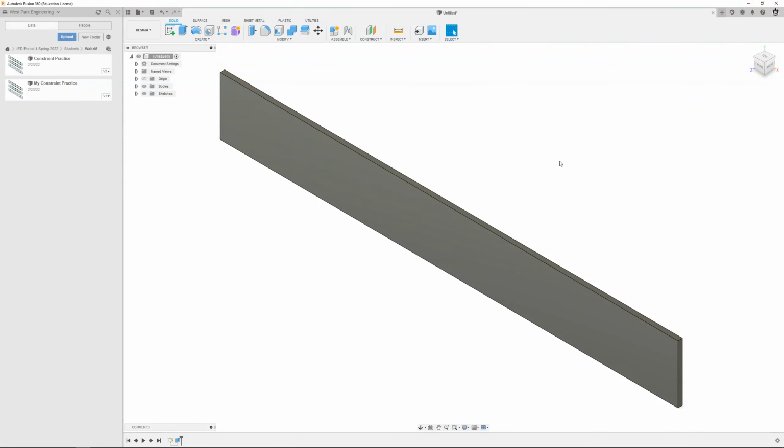One thing we want to do right now before we save it is set up the material settings and the appearance settings. So we want to make this thing wood, basically. And it doesn't actually matter that much. It'll still make the ruler the same way in the laser cutter, but it makes it look realistic. And if we were interested in the strength or physics or anything of the ruler, it would be helpful.